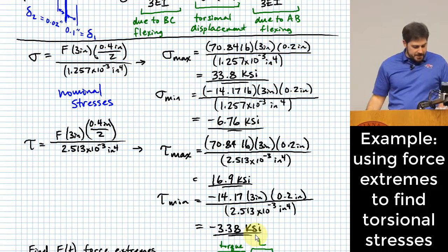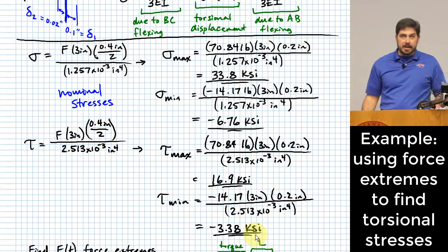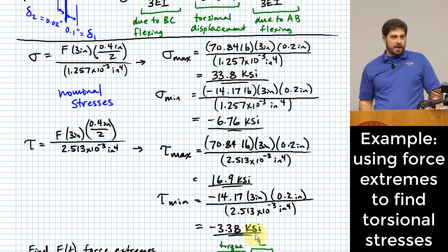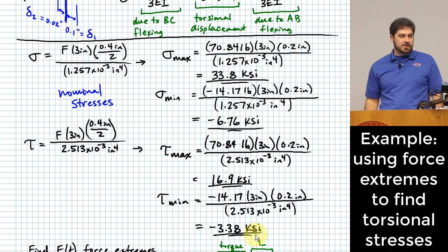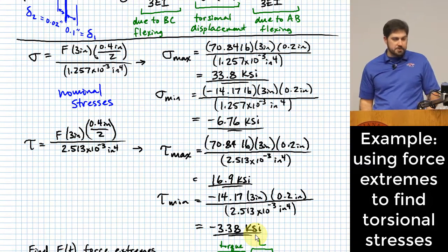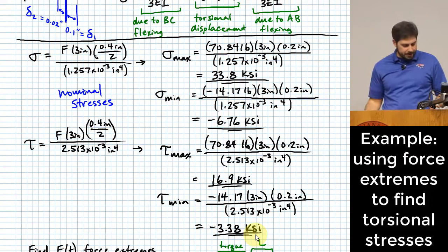What you'll notice is that these equations build in your stress concentration factors. So if you want to use them directly, you want to find your mid-range and alternating stresses as nominal stresses, not as fully computed maximum stresses, right? Because it has those incorporated into these equations instead of doing them separately.